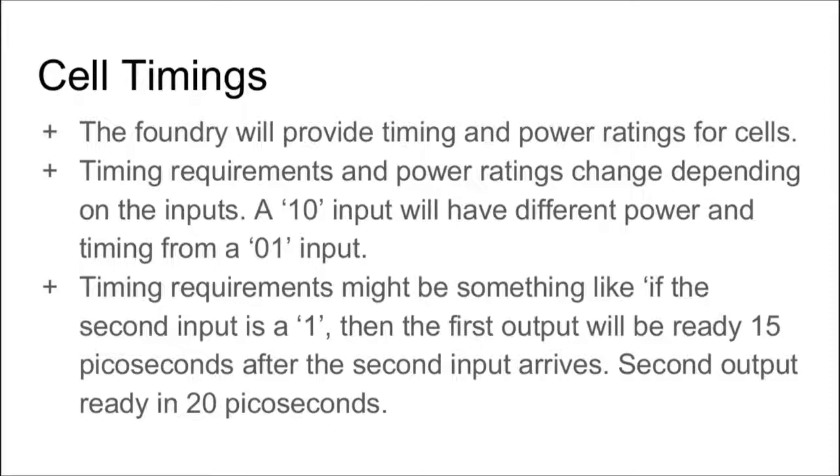And so if you know that within your circuit you have a lot of gates where you really need to reduce the time, where the second input's going to be really late and you need the second output to be ready as soon as possible, you can actually reconstruct the physical components of your gate to optimize that.